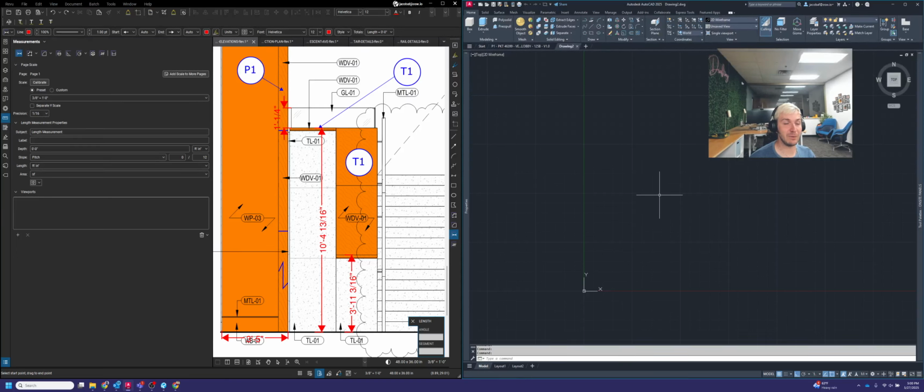If you ever need to import a PDF, let's say you need to bring in a logo, a floor plan, even just a detail, maybe a light fixture, hardware, something like that. If you ever need to bring in a PDF and turn it into lines in AutoCAD, as long as it's a vector PDF, you should be able to use AutoCAD's PDF importer. So all you do is type in PDF import. It should come up here in red. You're going to click on that.